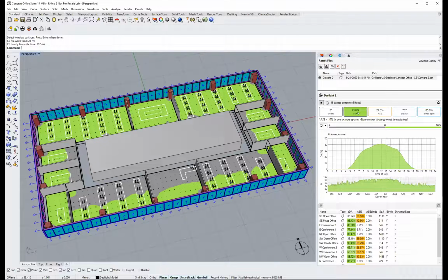But actually there's an asterisk here, which is important, which says that we have an excess of annual sunlight exposure. Now, if we had been doing this calculation versus LEED 4.0, we actually wouldn't have gotten any of this daylight autonomy credit because of the way the accounting works. We would have been docked or penalized because of our excessive ASC.